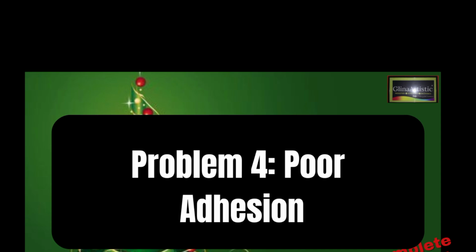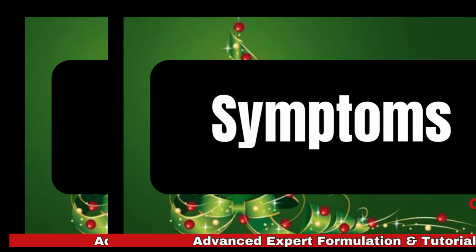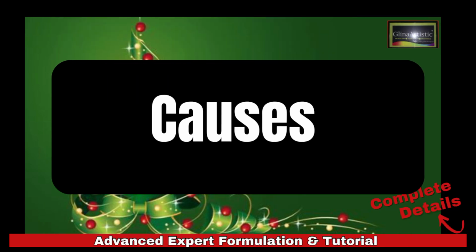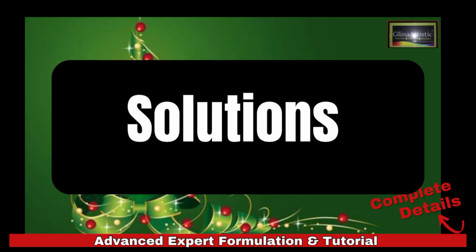Problem number 4: poor adhesion. Symptoms are paint peeling off the surfaces. What are the causes? Low quality binders or poor surface preparation. The solution is simple. Use your high grade binders like acrylic resin or alkyd resin. And then of course, clean and prime the surfaces before application, before painting.